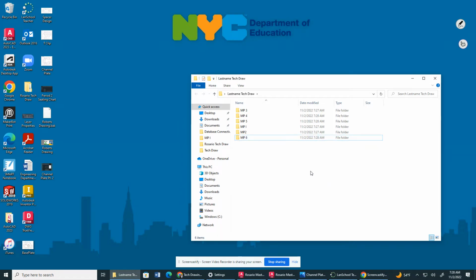All right. So, reason being we're going to do it like this is because each marking period we're going to have a set of projects and assignments. So what we're going to do is basically put each one corresponding to the assignment. Now, reason why we do this is because it allows us to, one, have a master file where we have our layer properties set, and we get to create our drawings off that master file and save as.